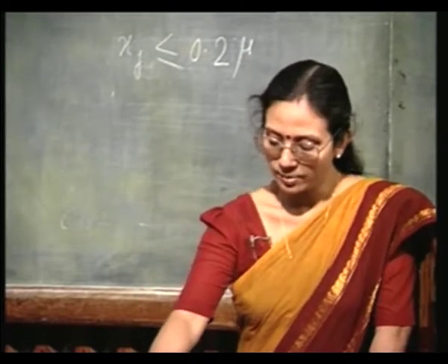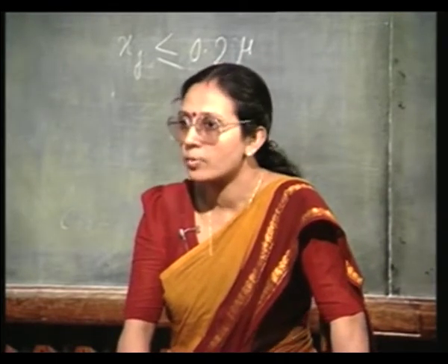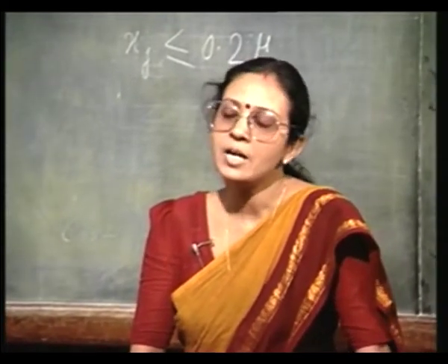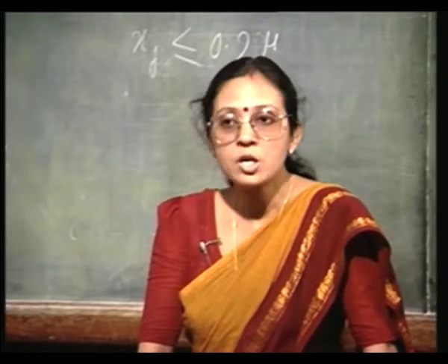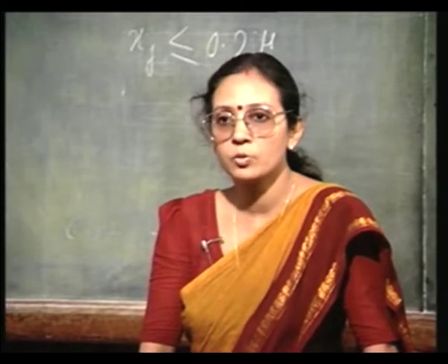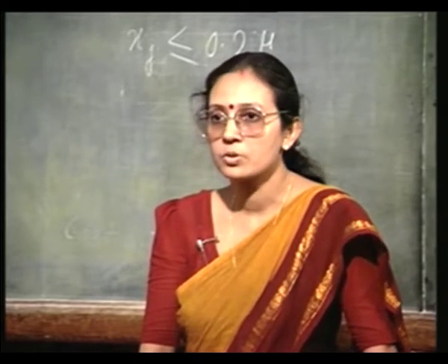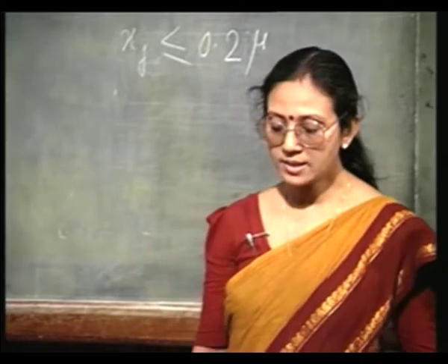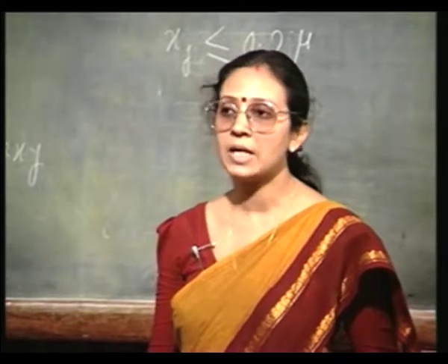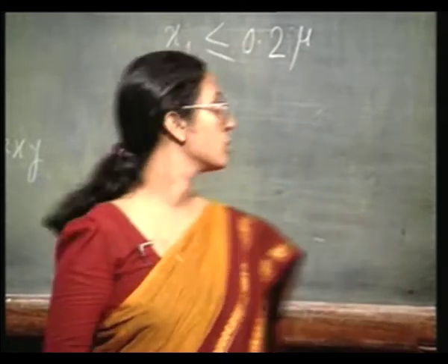Well, I cannot do much about boron being a light atom. Can I do anything? I cannot do anything. It is a property of the material. Boron is a light atom. I cannot wish to make it heavy. However, I can play a small trick. I can use molecular boron. Instead of using atomic boron, I can use molecular boron, so that the weight problem is to some extent reduced. So, one thing is you implant from a molecular boron source, for example BF2, so that your projected range, RP, is reduced.